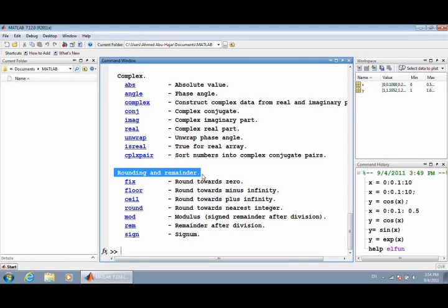So you always have to round your number to 16 bits or 8 bits or 32 bits and so on. They become very important when you implement algorithms on a DSP microprocessor, and that becomes very handy and very powerful for us.